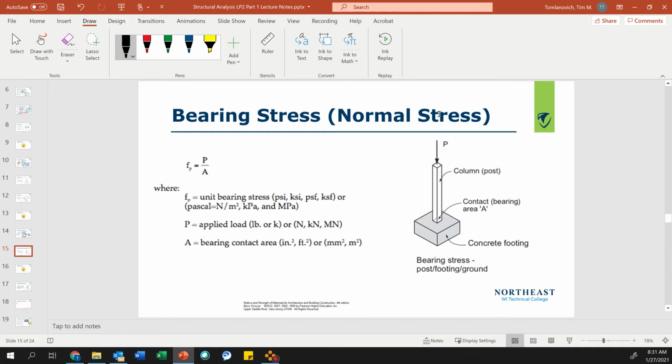So it's my recommendation that you get us geotechnical engineers involved early, because what happens if I can't put it on a shallow foundation? I have to put it on a deep foundation. Your design is going to change. So unfortunately, you have to go through the load tracing. Here's my preliminary design, and then I'm going to look at the site that I want to build on. You want to do some soil borings, and we want to see, based on the size of the structure and the loads of the structure, will this foundation work?